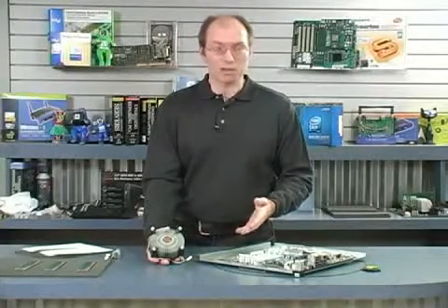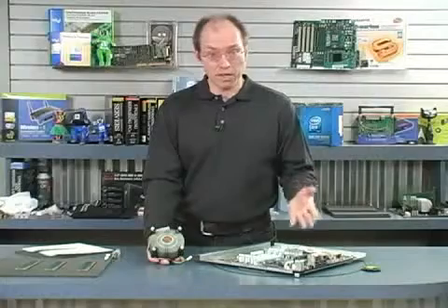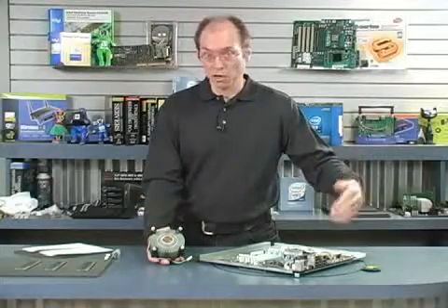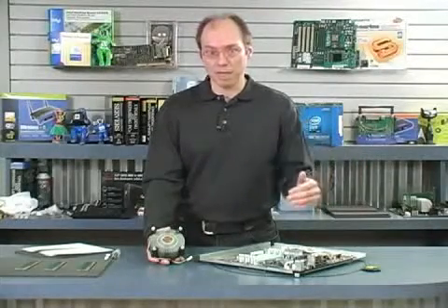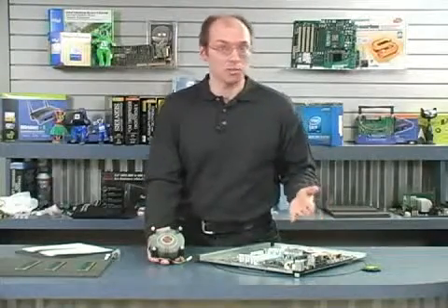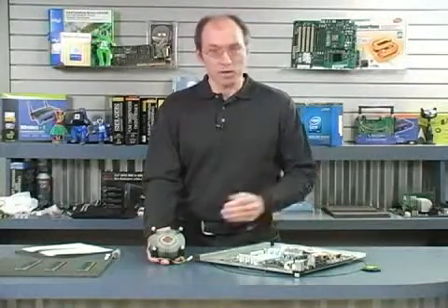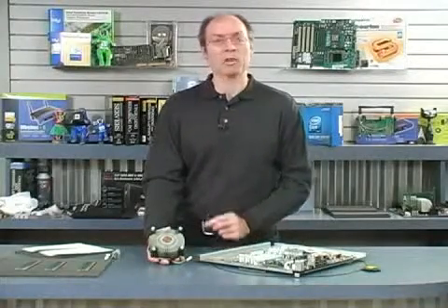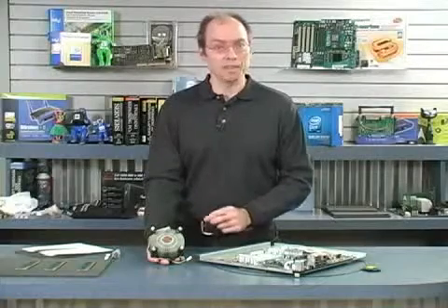And what that'll cause is that in many cases the processor will overheat or not be able to run at its full speed, because modern processors don't actually overheat to the point of destruction or stopping. What they'll do is throttle themselves down. So you'll end up with a system that for some reason doesn't seem to be running as fast as it should. The real reason is, you don't have a good bond between the heatsink and the top of the processor.